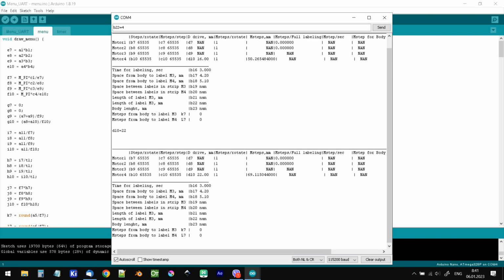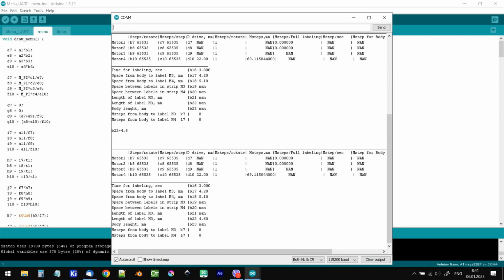But there is a dark side of power in such a menu. With so much text being output and edited by the controller, there is little cycle time left to process the main algorithm. Or if the controller is very busy with the main algorithm with frequent timer interrupts, then the menu may fail. So it is necessary to maintain a balance between different Arduino tasks.